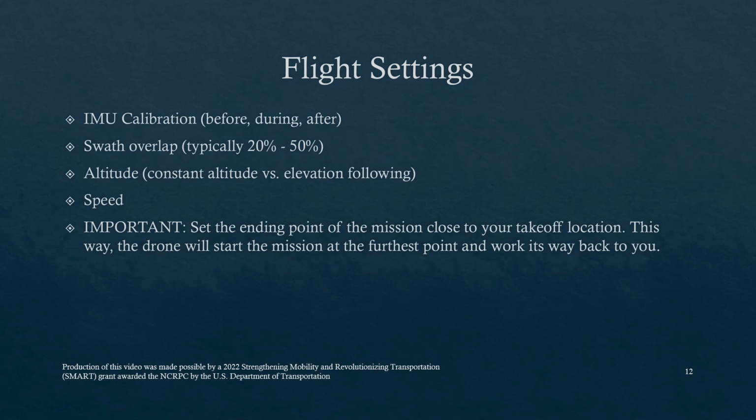And then also, it's important to consider and be mindful of your starting and ending location of your flight. You always want to try to start your flight as far away from you as possible so that it ends as close to you as possible. Because at the end of your flight, if you have a low battery, you want it to be closer to you rather than further away, especially with these LiDAR sensors, because they can be very expensive.